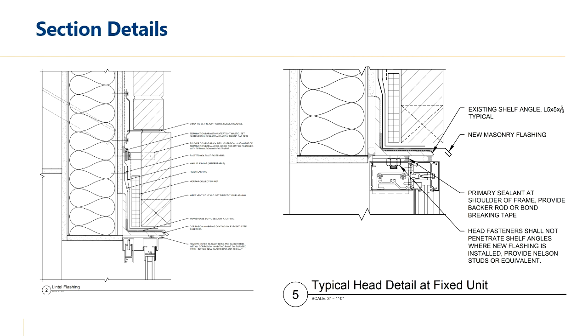And then on the right, we're paying attention to how that window is attached, so that we don't wind up with the window installer installing screws or things being installed upward and drilling through and compromising our flashing as well. So lots of great information you can cover in just that simple section detail.